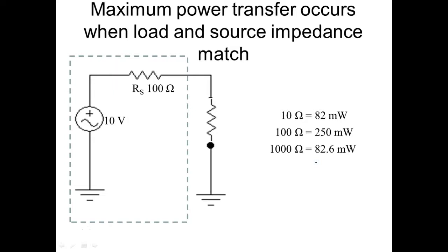But if we can match the impedance in the channel, then we get maximum transfer. So that means these cables, these coax cables, they have a certain impedance at a certain frequency, the frequency of the carrier. And then these twisted pair cables, they have a certain impedance, right, at a what? At a certain frequency. And if everything in the system matches, then that means you get maximum power transfer.